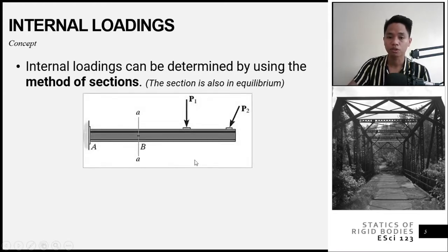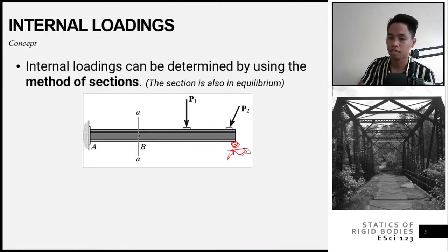Alright? So, for example, this is a cantilever beam. I hope you know these, I shared a meme about them in our group. You should know what a simply supported beam is, what a cantilever beam is, and what a simply supported beam with overhang is. Then there is another one, which we have not covered in our course, which is a prop beam. The same here, this is a cantilever beam, whereas a prop beam is a cantilever beam with a roller. That is a prop beam. But we will not discuss it here because that is a statically indeterminate structure.